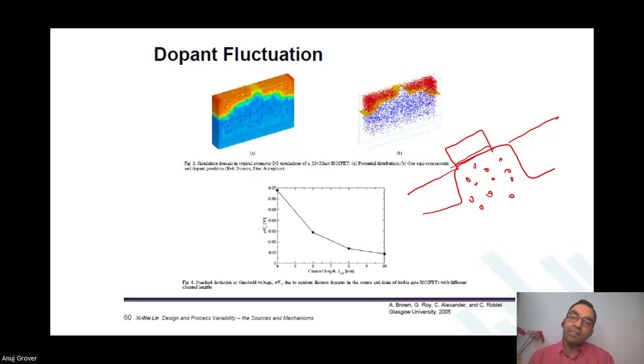It can also happen that instead of 20, there are 18 dopants. Now, less band bending is required for VT, and therefore you will see that the device is a little fast. Are you with me?